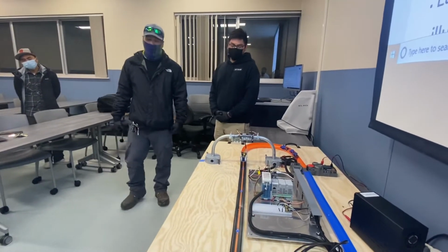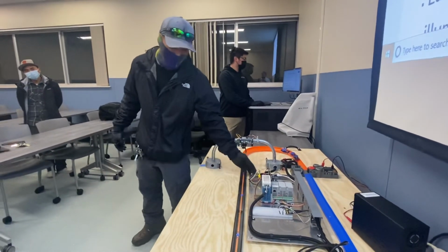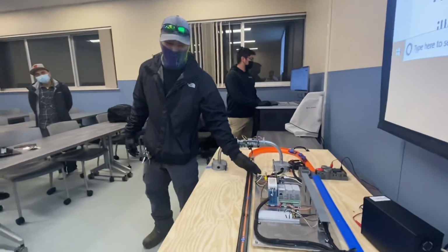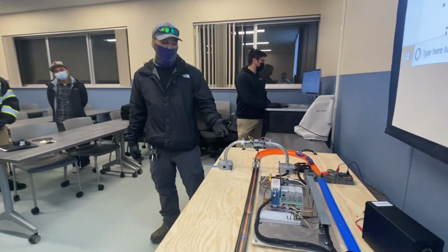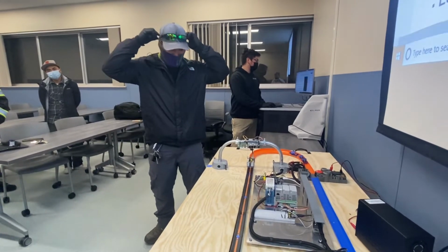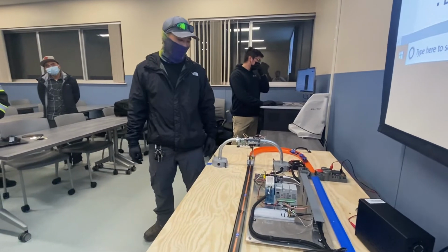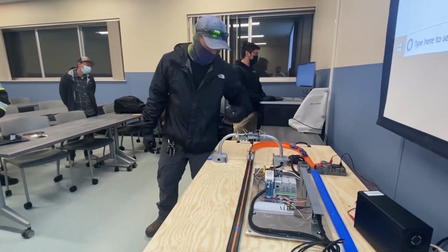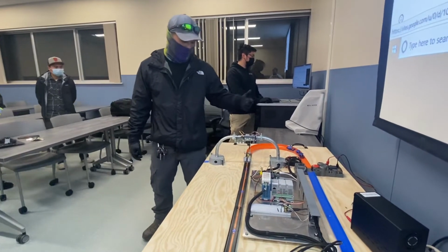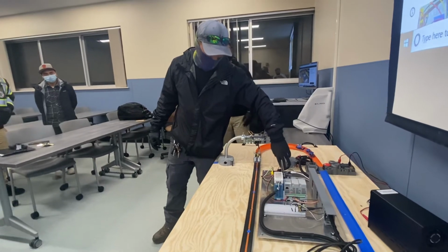Yeah, basically our reasoning too, as well. Obviously, we wanted to protect the wire. We're using aluminum plate over here. It has sharp edges on it. I didn't do anything to smooth it out, honestly. So the last thing we wanted was a short circuit or anything like that. So definitely our main goal was to protect the wiring, either from tension or from abrasion or shearing. So yeah, that's basically why we just ran it through a shrink tube, and we put wire loom over it